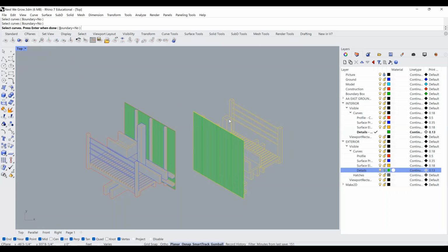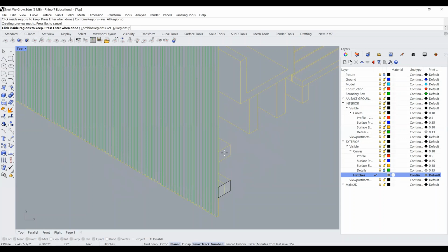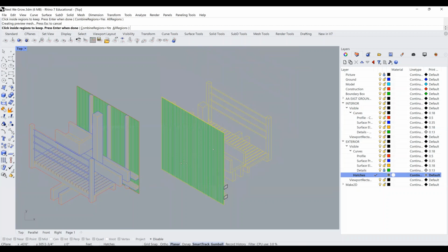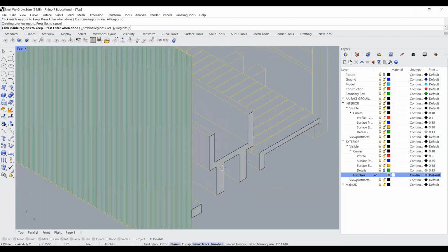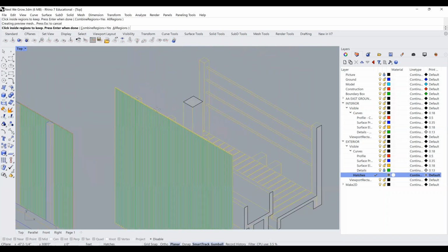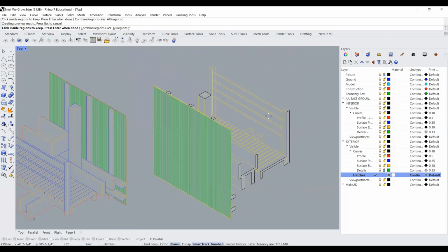What I've selected already is everything that is going to allow me to start making a hatch. So now that I've selected all the curves that I want to start hatching, I'm going to select the boundaries that I want to hatch into. I'm going to make sure that my check mark is on the hatches layer. And I know that for this, I cut towards the further portion of the section cut line, right? This is the exterior portion looking towards this way, if that makes sense. And so I'm just going to keep continuing and color in the hatches where I took my cut. This should be the areas that I cut. And remember that I cut both in this direction, and also in the far direction here, but you can't see that because of this angle.